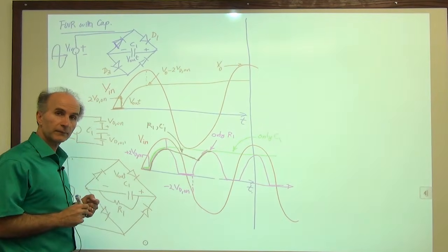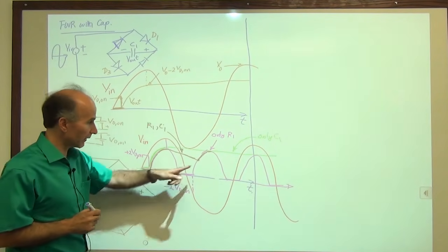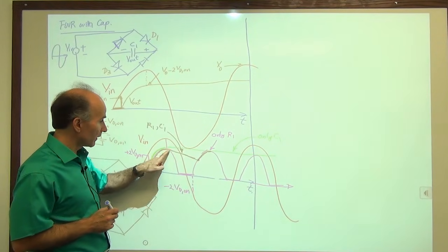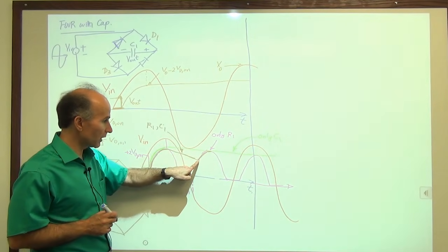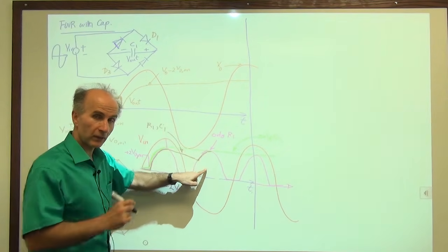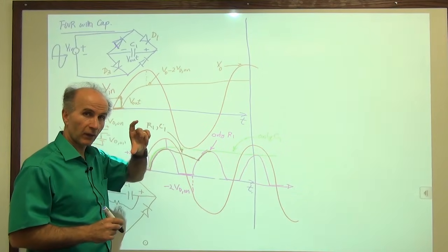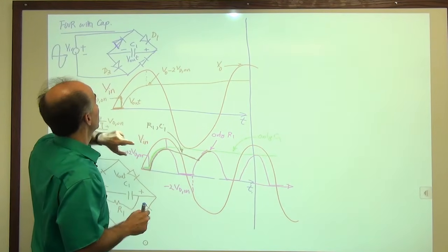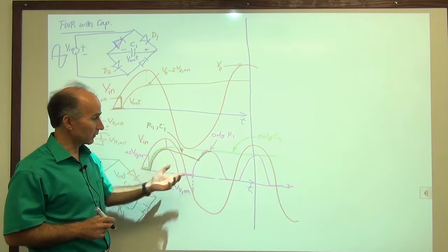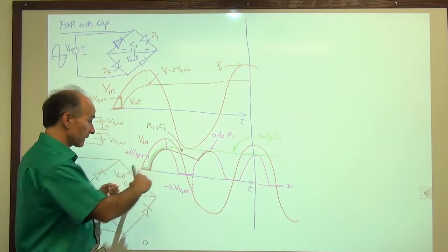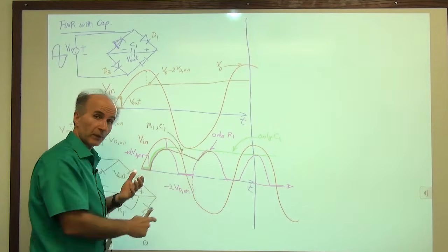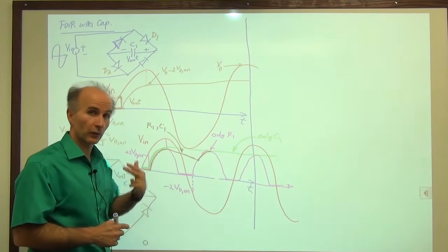Is this correct? I allowed the voltage on the capacitor to reach here, not further. For the half-wave rectifier, we said we needed a difference of 1 diode drop between the input and the output. What happened here? Do we need that? Well, this waveform already includes that. This is already the output waveform, right? So it already includes that 2 diode drops.